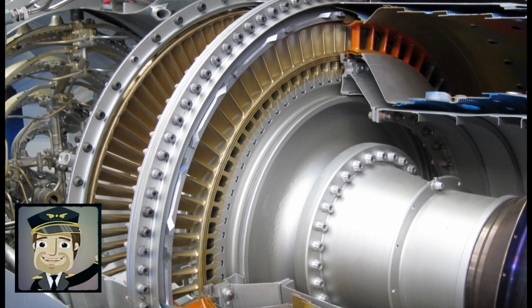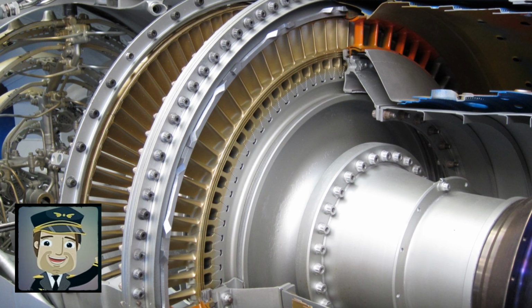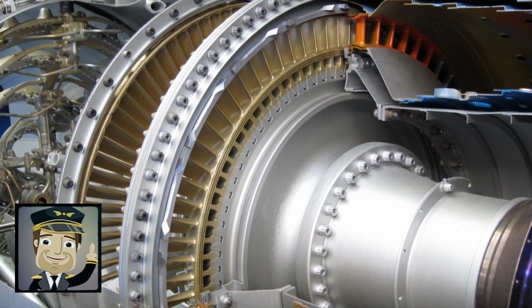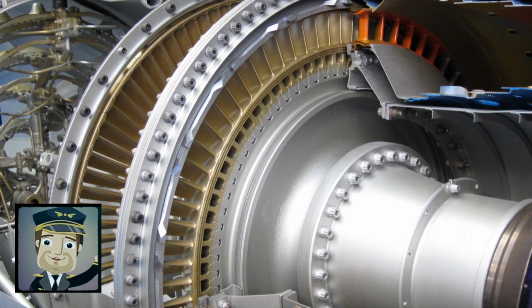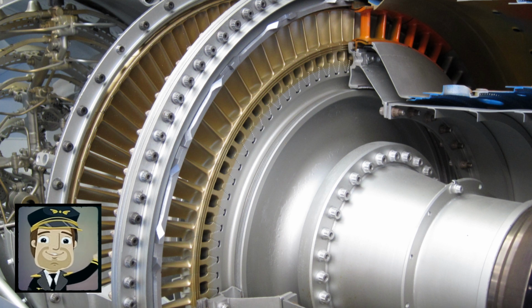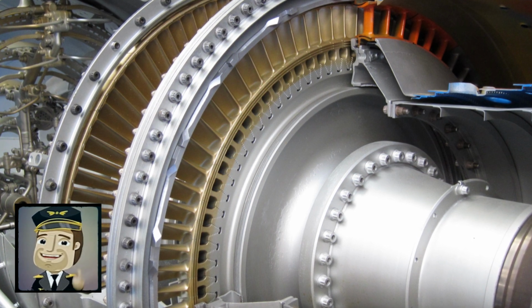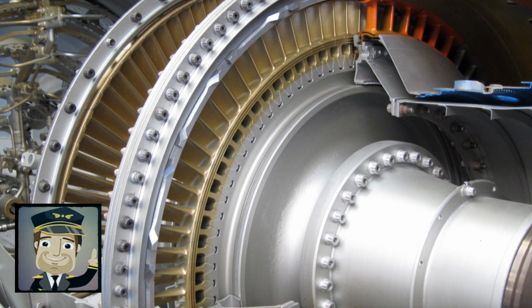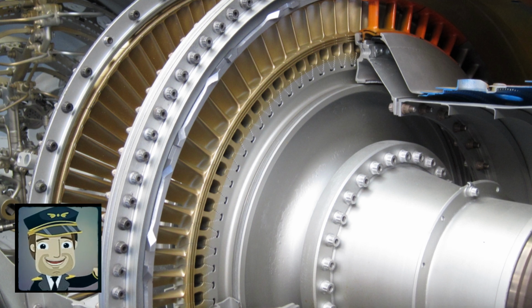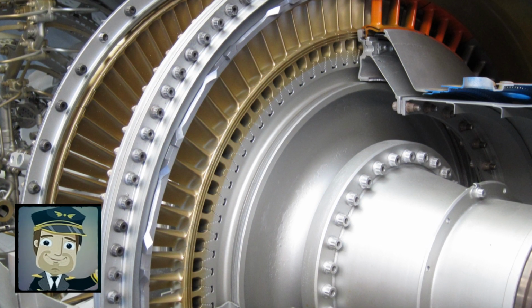Rolls-Royce engines have a 72 to 82% propulsive efficiency and 42 to 49% thermal efficiency, and aim for theoretical limits of 95% for open rotor propulsive efficiency and 60% for thermal efficiency with stoichiometric turbine entry temperature. As teething troubles may not show up until several thousand hours, the latest turbofan's technical problems disrupt airlines' operations and manufacturers' deliveries while production rates rise sharply.